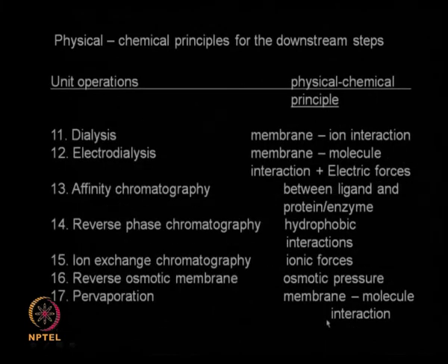Let us continue some more. Dialysis, there is a membrane and ions are interacting with that. So, the ions get separated. Dialysis is very good for separating salts from a solution. Then we have electrodialysis, where you are using an electric force. So, the separation is not only a membrane interaction, but there is also an electric force applied, so that positive charged material will go to the cathode and a negative charged material will go to the anode.